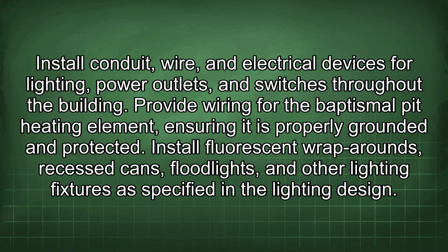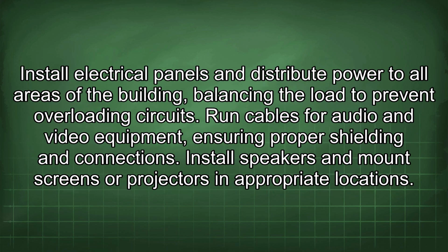Install conduit wire and electrical devices for lighting, power outlets, and switches throughout the building. Provide wiring for the baptismal pit heating element, ensuring it is properly grounded and protected. Install fluorescent wraparounds, recessed cans, floodlights, and other lighting fixtures as specified in the lighting design. Install electrical panels and distribute power to all areas of the building, balancing the load to prevent overloading circuits.